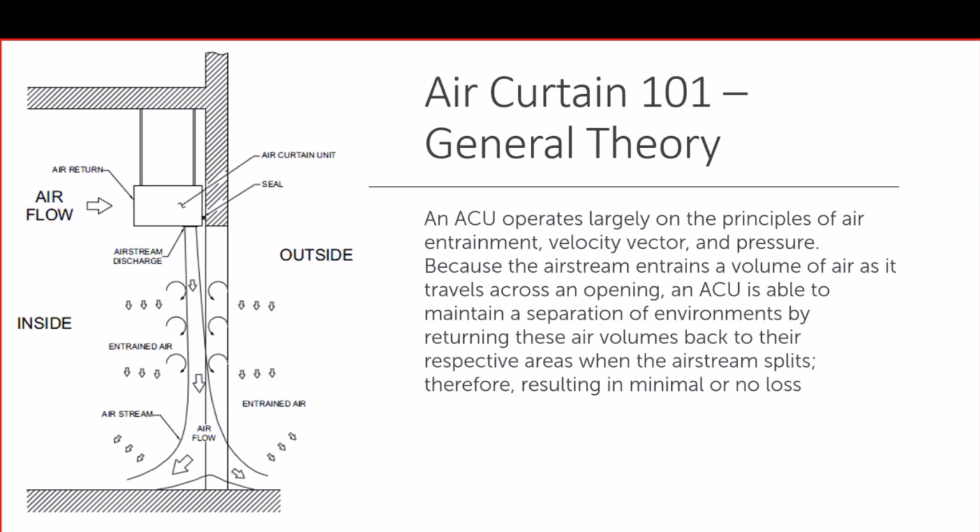Okay, for an air curtain to work, there are certain characteristics that the airflow should meet. It should be very laminar. You should have a uniform airflow across the discharge, and there are other technical criteria that the airflow should meet. That is one of the reasons why all air curtains are not similar. There are air curtains that are designed much better than others and will be much more effective for your application.